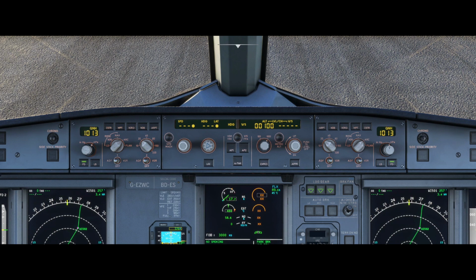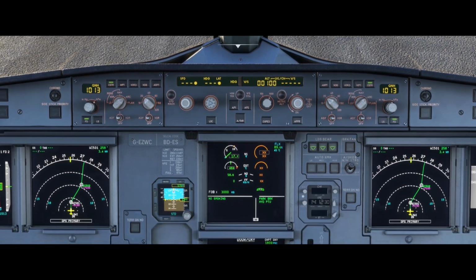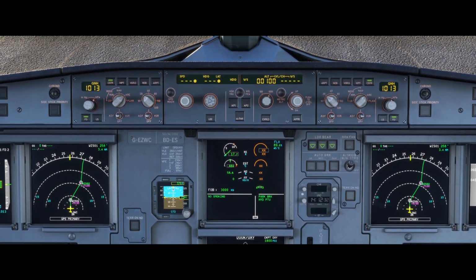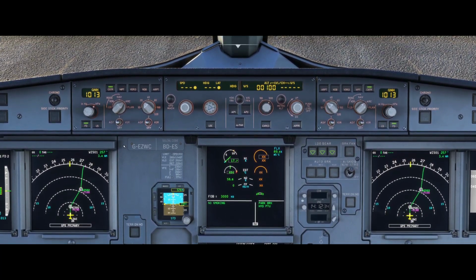First of all, this little switch on the left, that's to play around with the QNH and the pressure settings. Obviously when on the ground we would select the current pressure setting we'd get from the ATIS weather or from air traffic control, and both pilots will need to select this and make sure they're on the correct one. Twist knob here, we can increase or decrease it, or we can pull it to go on a standard pressure setting once we're flying a little bit higher at flight levels.